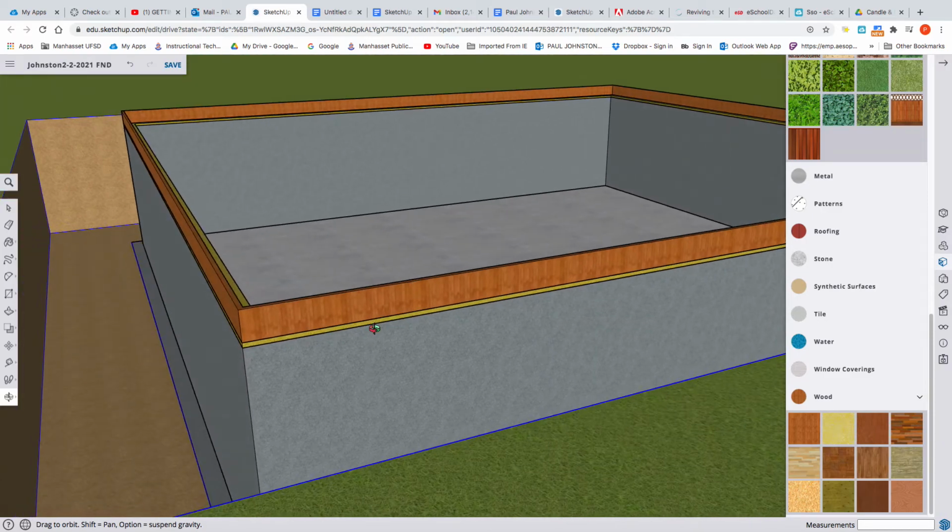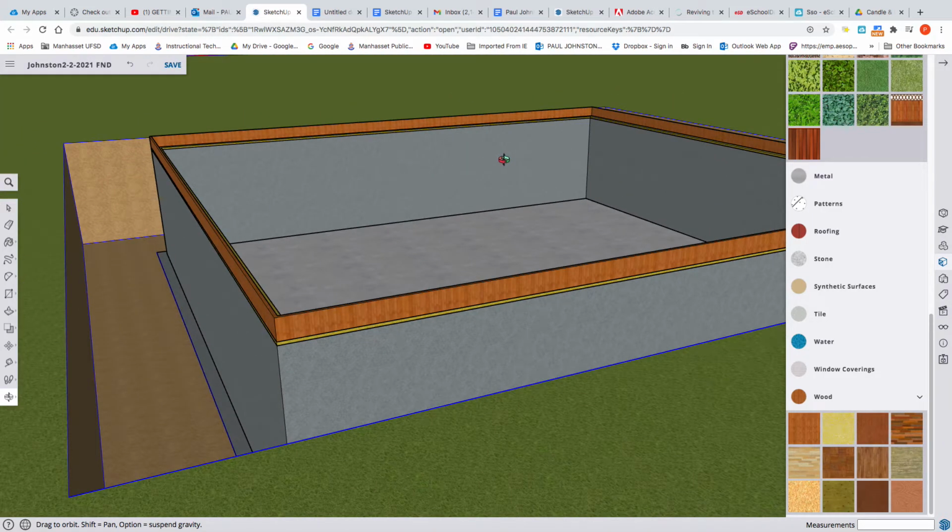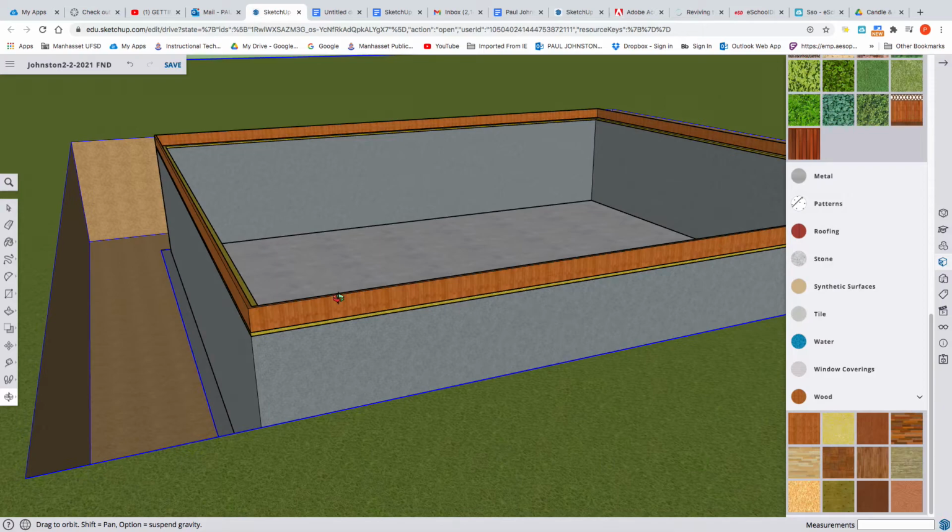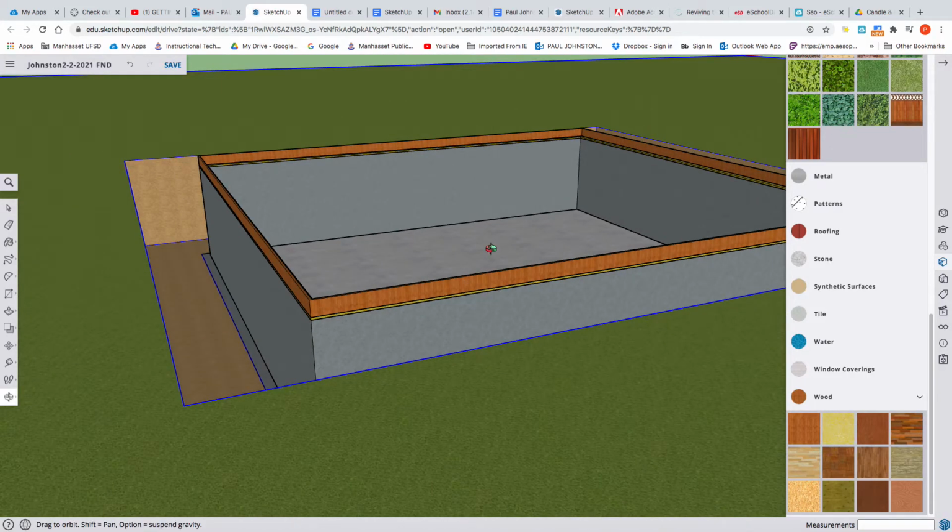And then we have to make the floor joist. That's the structure of the floor that's in here. This is called a ring joist because it goes all the way around in a ring around the outside shape of the house. If the house was L-shaped, this would go around the whole thing in an L shape. So that's called a ring joist.